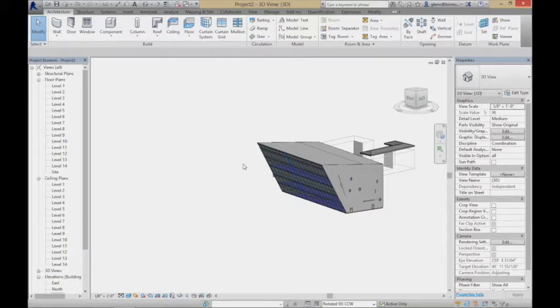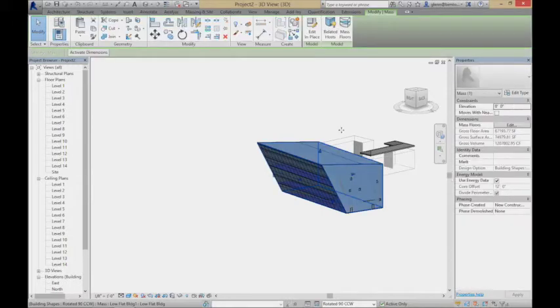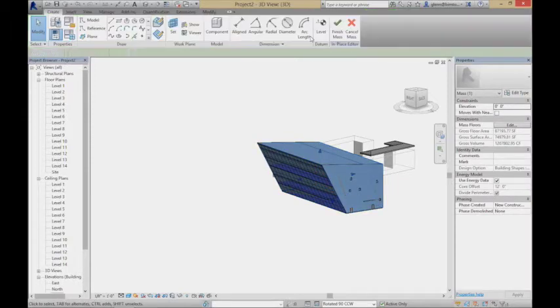You know, you may go ahead and decide later on that your conceptual mass just isn't quite right. You want to go through and make some changes to it. Let me just show you how that works, because that's possible too. The mass is here. You just can't see it. It's kind of buried alive under all these building elements. If I tab a few times, I can get it. I can tell down in the status bar, down in the lower left-hand corner, I can see it's a mass, low flat building. I'll choose it. And I can edit that.